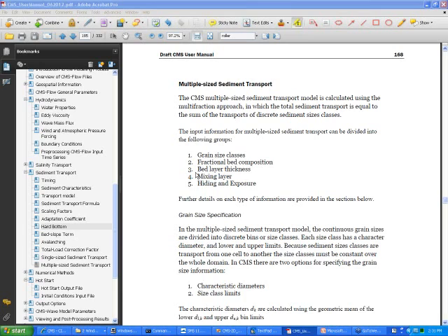And that can lead to errors in the wave height in the near shore and can cause spikes in the sediment concentrations. Also, some formulas are more prone to instabilities than others. For example, we've seen that the Lundgren formulas tend to cause spikes in the near shore when you get really, really shallow, like less than 20 centimeters. Soulsby and Van Rijn tend to not do that as much.